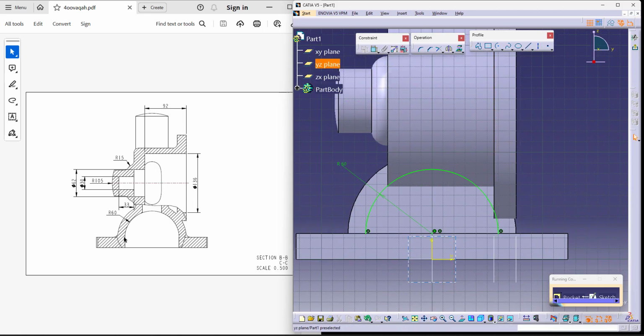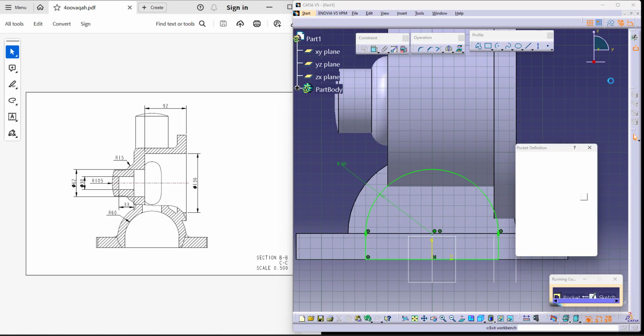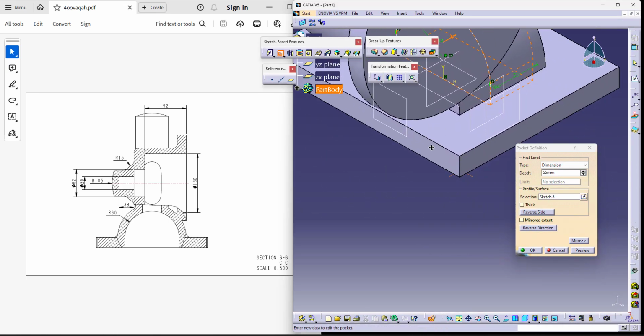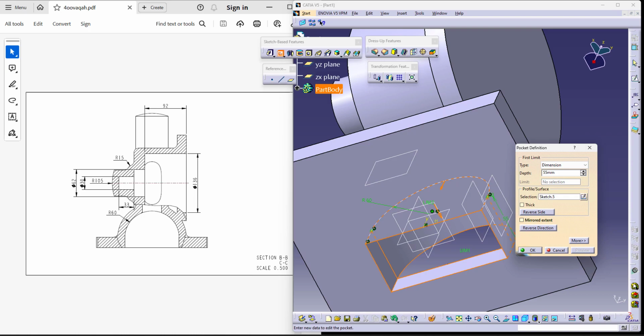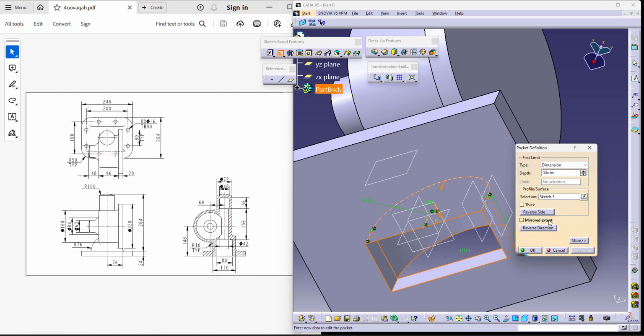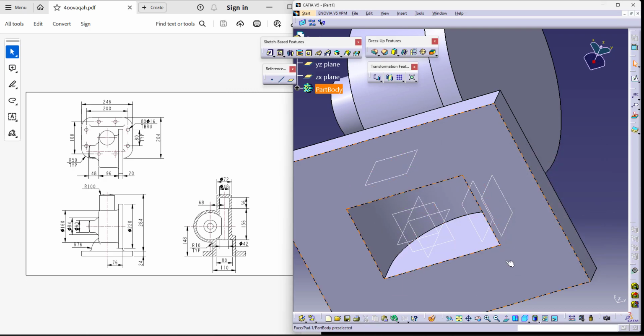As you can see, the cut has a straight line and then a closure. So let's try to do that as well. Considering this as the end point, this is the closed area. Now once I exit, it tries to remove the material from the bottom side. I'll just show you the preview. It has to be done on both the sides to only up to 80. So I'll say mirrored extent to up to 40. So it does cut material on both the sides this way.